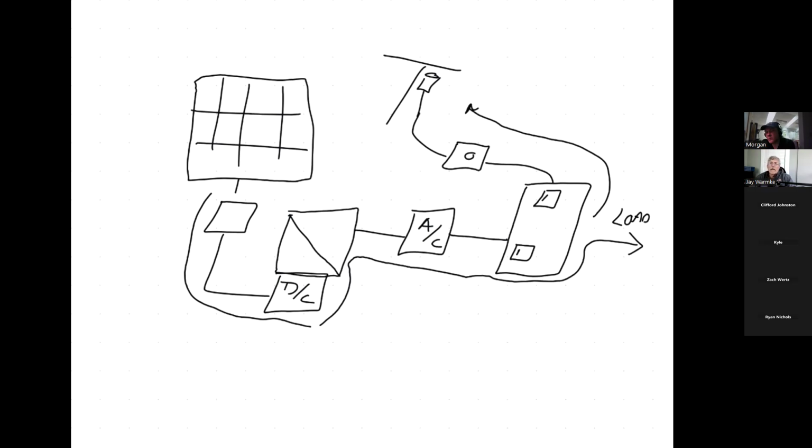Well, how do you compensate for that if you're a grid operator? You should think about the voltage sort of like water pressure. I keep using the water analogy, but it's pretty good. So the grid has to operate within a range, plus or minus 5%, plus or minus 6%. This is how they control loads as loads are turned on or turned off. Because if I turn on a light in my house, it slightly reduces the voltage of the entire grid.